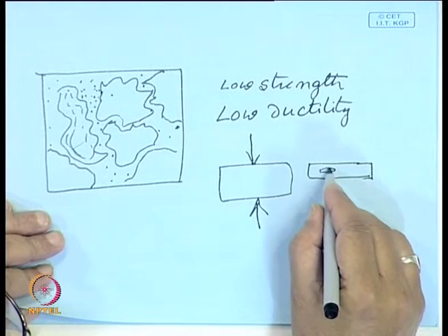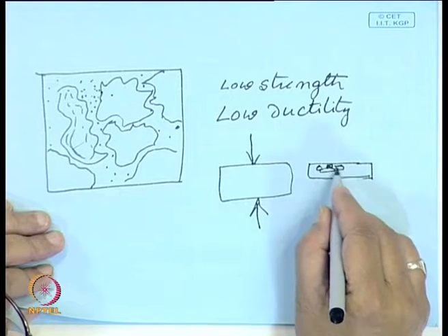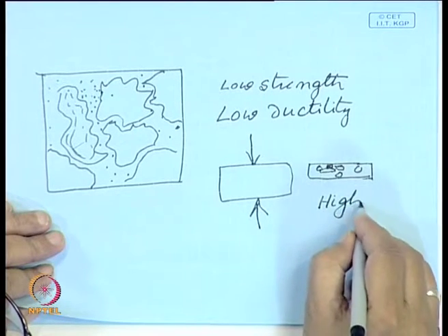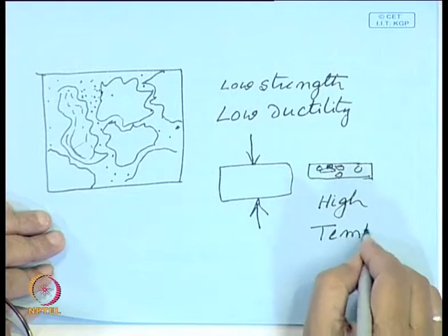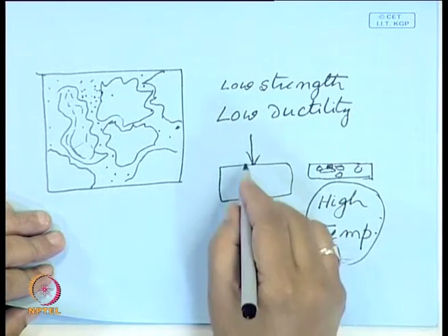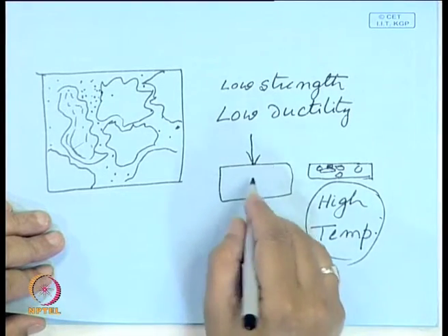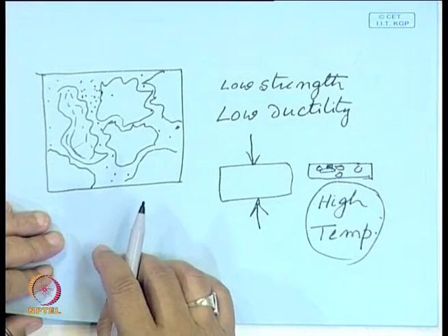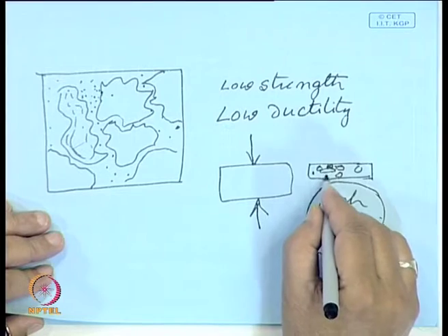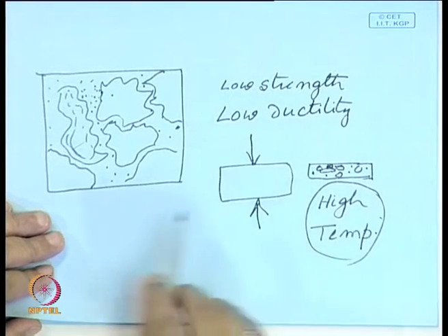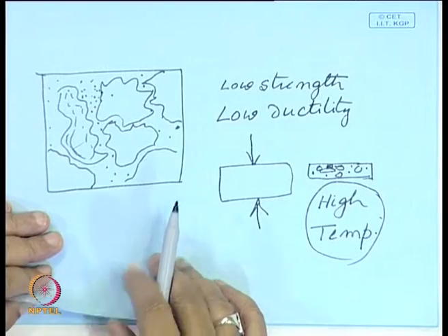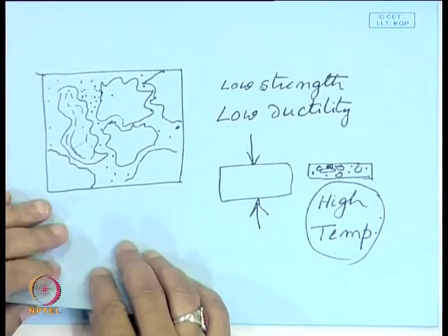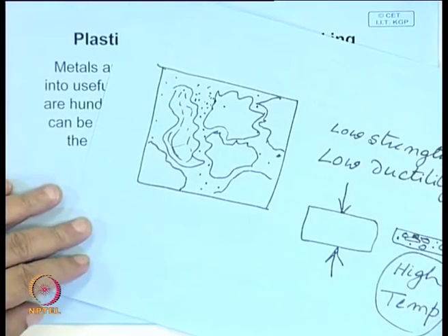So, the grains deform also, they recrystallize, and most of this primary processing is done at high temperature. At high temperature, as we go further we will see, the stress required to deform the metal is also very low, and this helps you get a uniform structure which is ductile and more usable. And by this processing, it can also be given different types of shapes that we need.